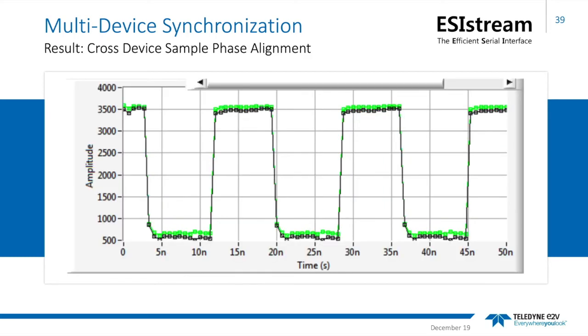Here's two sampled signals in perfect phase alignment. In this diagram, the green and the black waveforms represent two separate sampled channels. The sync chain helps ensure that both sampled channels are time aligned, irrespective of whether they are neighbouring channels within a single data converter or local channels across an array of data converters. This is sync chaining in action.